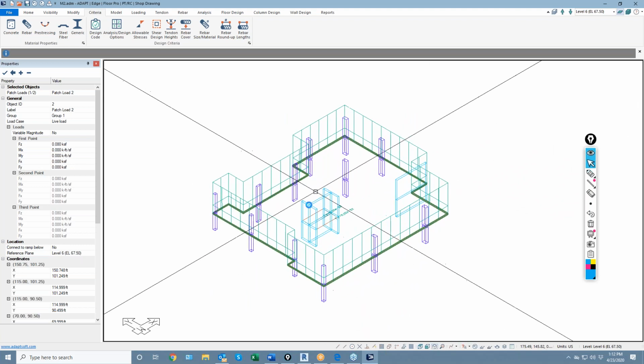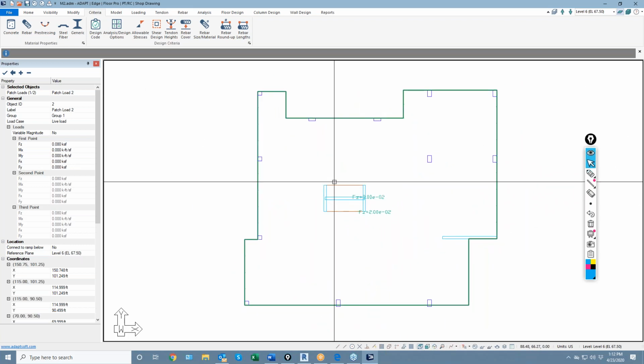Let's go back to the layout of strips. Now, the post tensioning in this program is flexible, meaning it's really customizable by the user. How do you want to lay the post tensioning out? There are replication tools, and there are ways to go through and more easily adjust and modify the cables, but at some point you have to enter those cables into the slab. So we first have to determine which way we're going to use for banded cables, and which way we're going to use for the distributed cables.